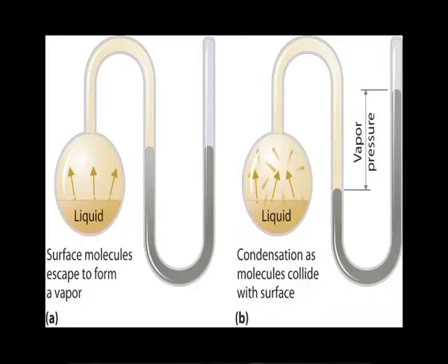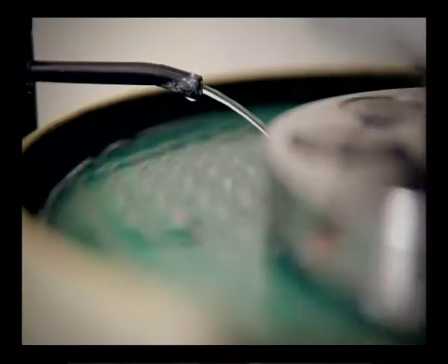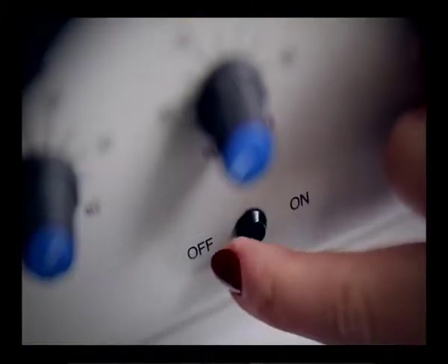The drying process as a whole has to involve the generation of vapor, transforming from the liquid phase in the moist material to the gaseous phase on and within the moist material being dried, and the transport of the water phases towards the outside of the material. Some debates are around how liquid water may move within the material structure.